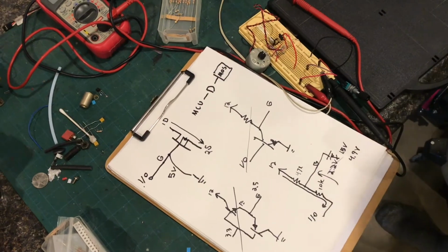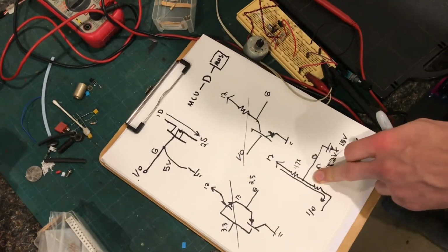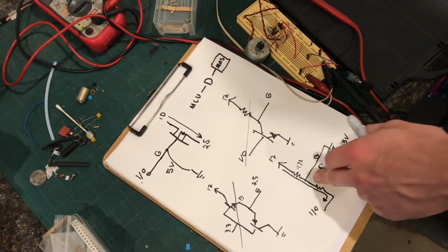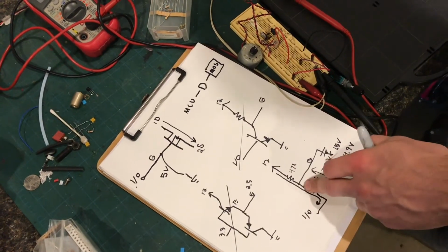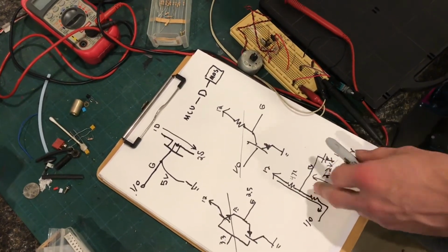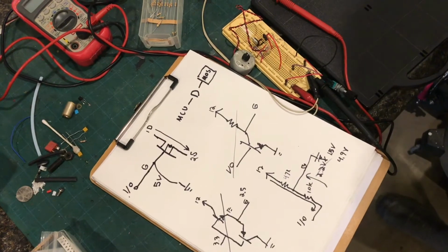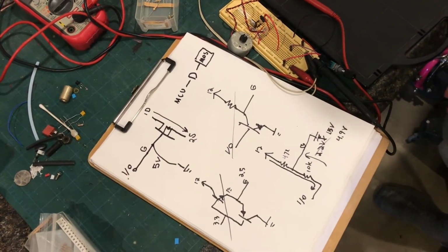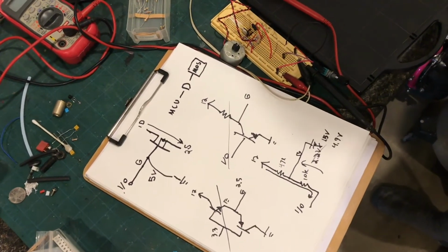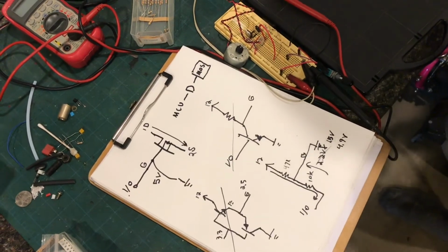Now, I was concerned that this might not work with the PWM signal that I'm driving it with from the microcontroller, but it's only a couple hundred hertz, which is really, in the big scheme of things, pretty slow, and it is working pretty well.